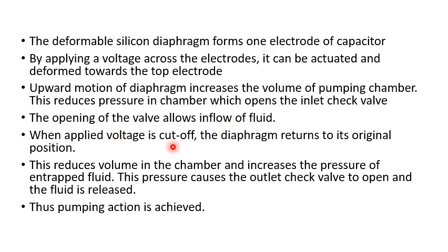When the applied voltage is cut off, the diaphragm returns to the original position, so the volume of the chamber reduces. It increases the pressure of the fluid inside, causing the outlet check valve to open and the fluid is released. That is how pumping is achieved.